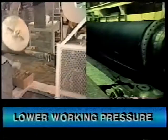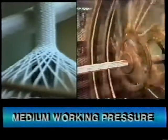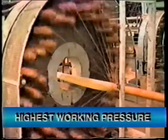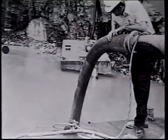Machine-wrapped and hand-built hoses generally have lower working pressures. Vertical braid and spiral non-mandrel-made hoses have medium working pressure ratings. Mandrel-built horizontal braid construction has the highest working pressure rating. The ability to withstand vacuum is generally due to a spiral helix wire included in the reinforcement. The vacuum rating is expressed in inches of mercury. Suction hose is usually horizontal braid or hand-built construction.